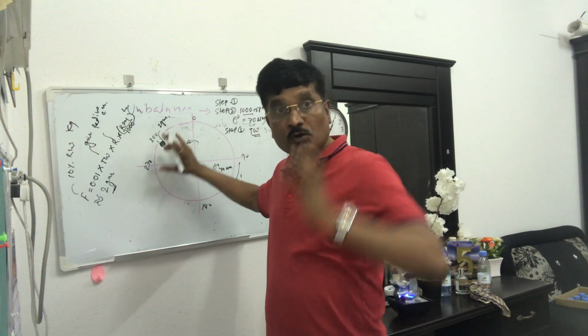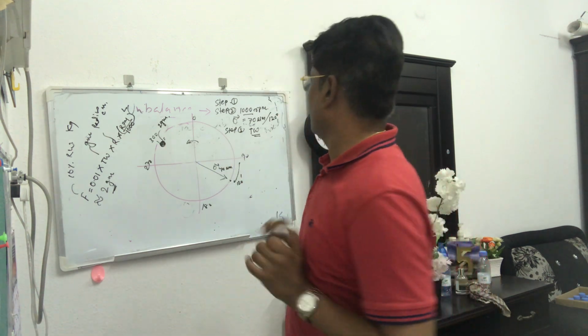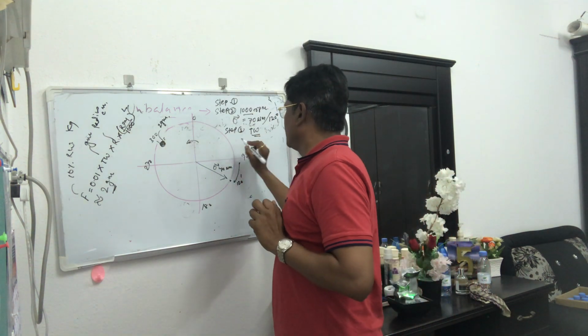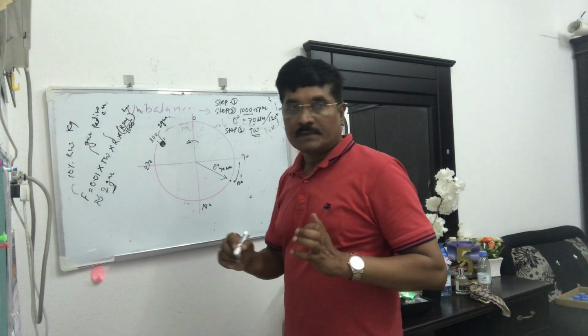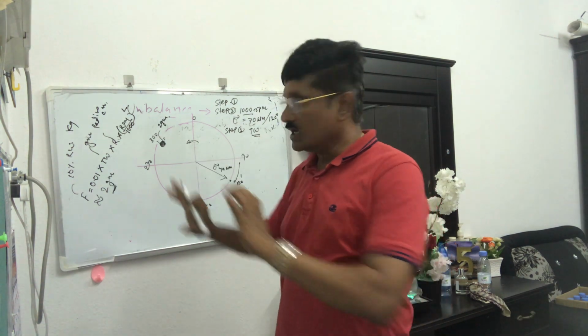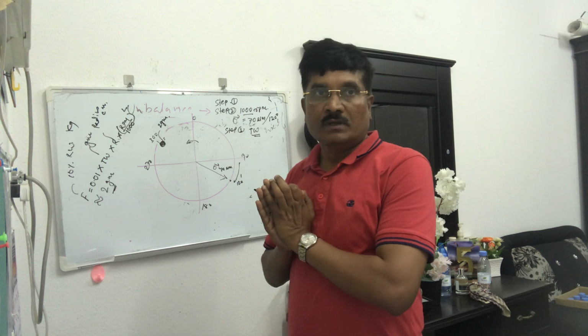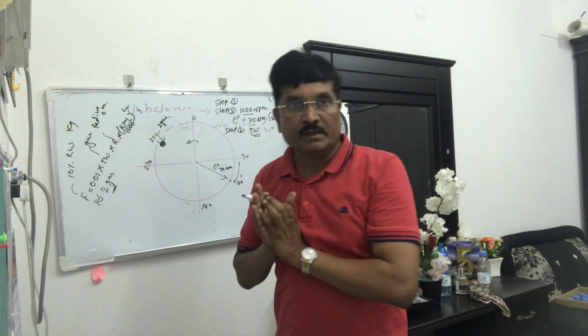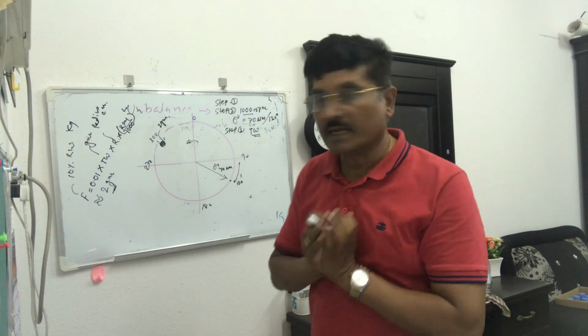Okay, this is the trial weight. We have to remove it afterward. Keep that in mind. This is our step 3. Add the trial weight. After adding, check all the safety provisions there, properly cover the coupling, all these things, and run the machine again.